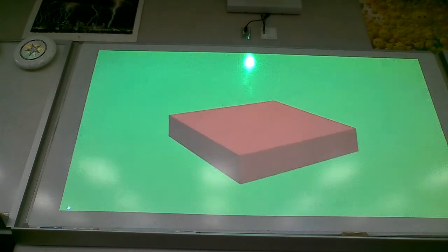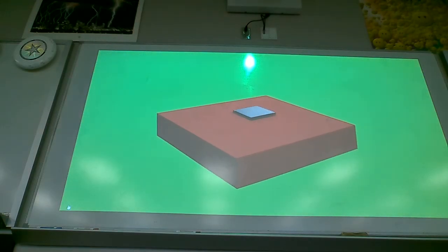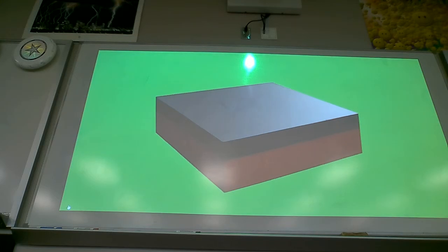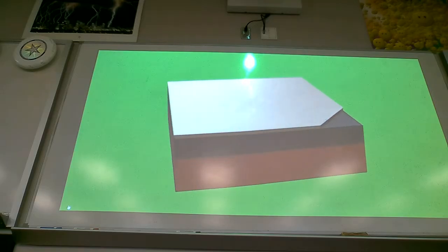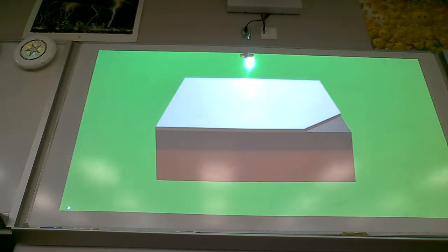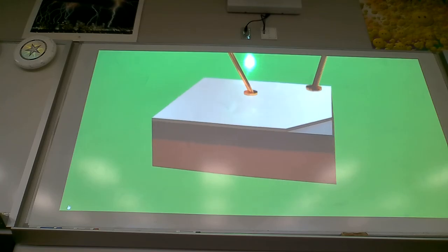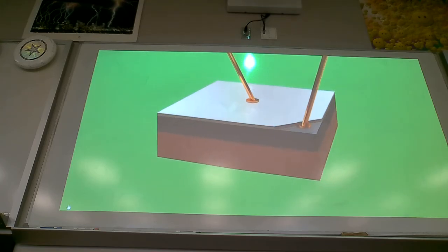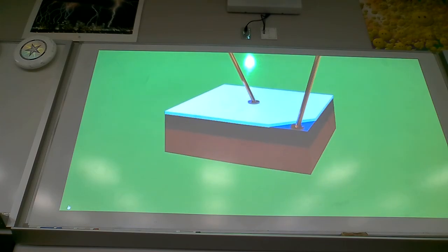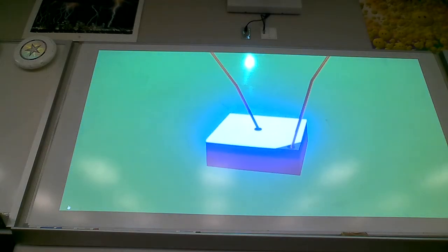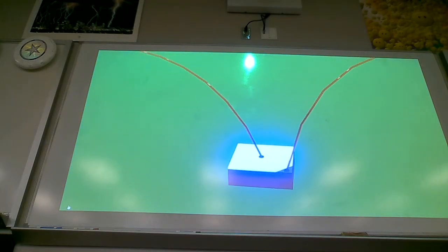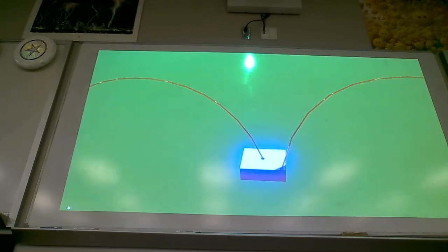The first thing we will need is a substrate where we will put the rest of the materials. To this, we add a layer of N-type semiconductor and then another thinner P-type semiconductor layer. The order is important because the transformation of energy occurs when reaching the latter layer. Then we add some cables so that the electric current can flow between the semiconductors and the light is emitted, being extremely thin so it doesn't cover it. Technically, only with this we already have a functional LED.